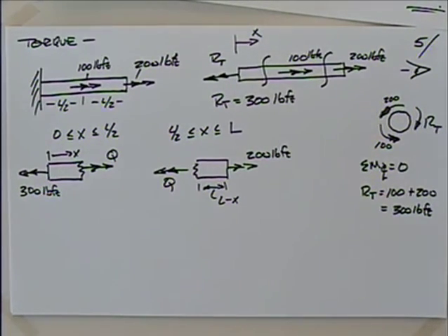Great application of distributed torques would be like an auger or something that's moving material along. It tends to increase its torque as it goes. To some extent, a camshaft or a crankshaft, as you apply load to it at each journal or lobe, has a distributed load on it.